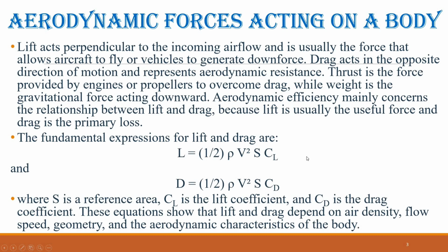The fundamental expressions for lift and drag are lift equals 1/2 multiplied by air density multiplied by the square of flow velocity multiplied by reference area multiplied by lift coefficient.